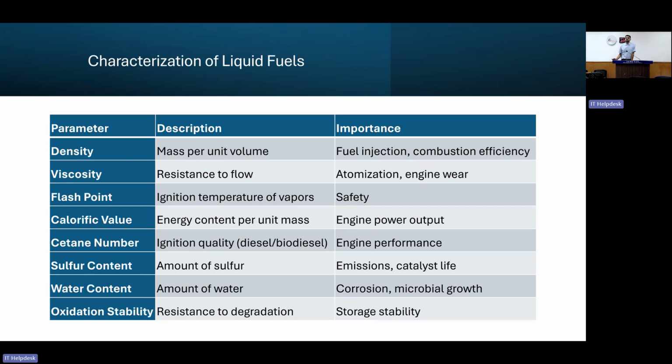And these are the characteristics of the biofuels in liquid form, considered for characterizing it as a suitable liquid fuel. These parameters include density, which is important for fuel injection and combustion efficiency. Viscosity is a very important parameter for the atomization process and engine bearing wear.